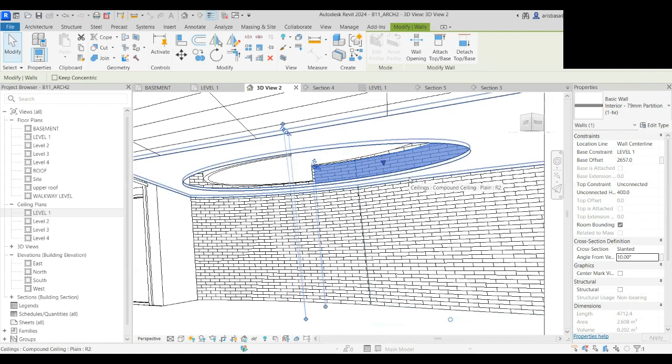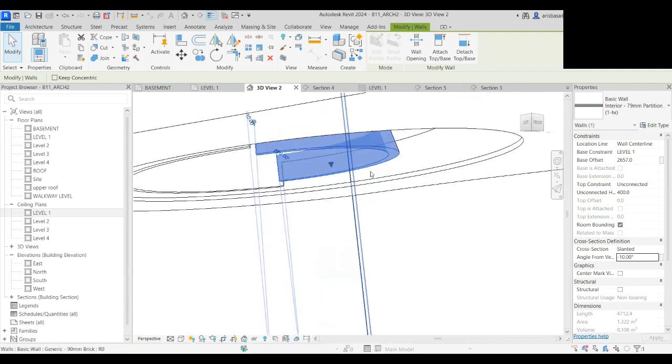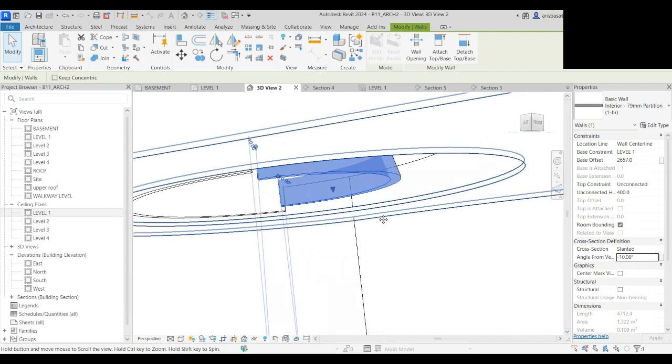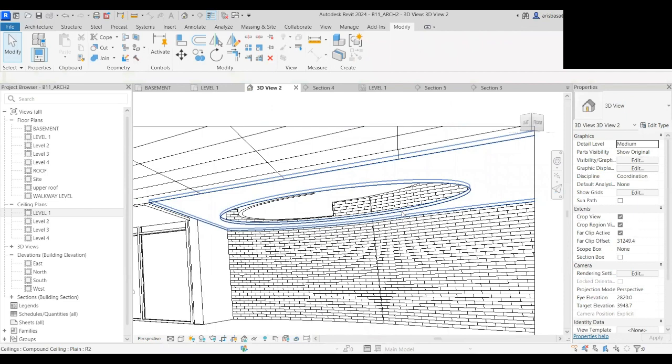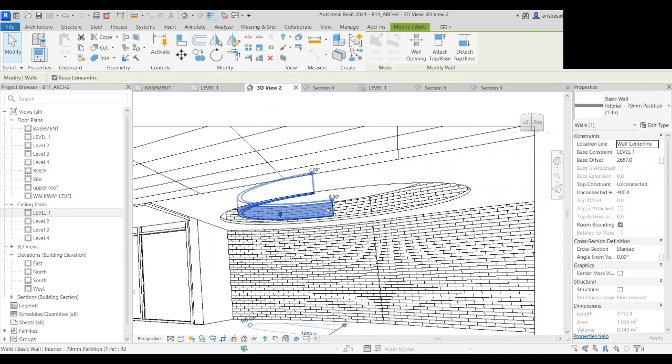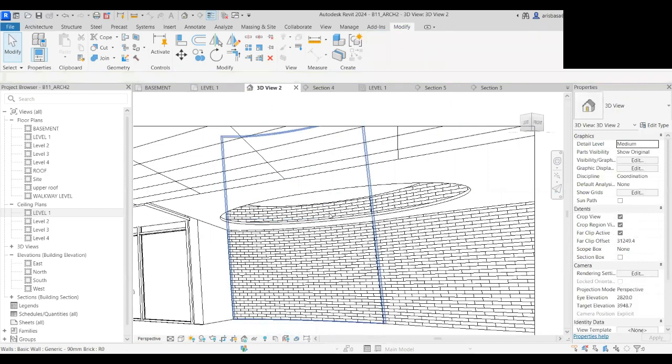It went like that. So can we make minus 10? Minus 10. The radius will decrease. Yeah, based on that gap. So it will not work based on the Revit rules. This slope works if we try it again on the other room, or rectangular or polygonal. It will work. But for circular, it's a bit difficult. So let's do something else for here.